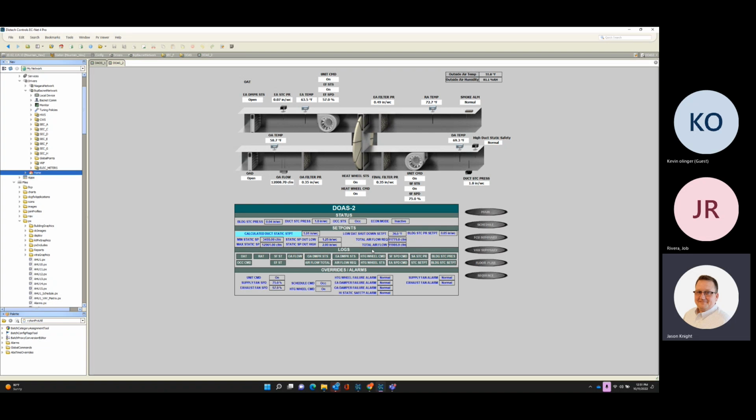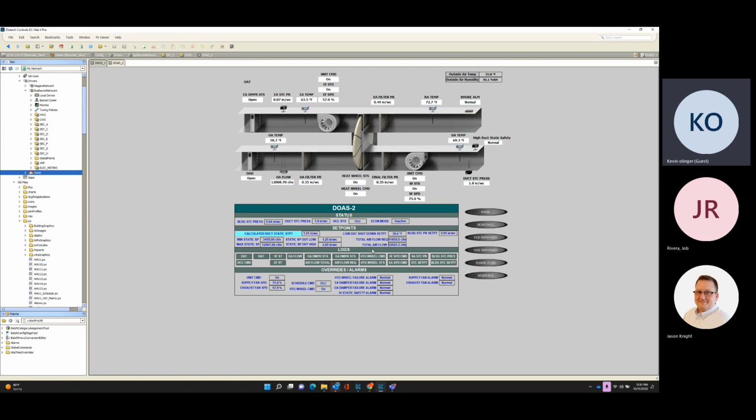Yeah, because typically what they've done in the past, like in a lot of your other buildings, is guessing. The specs all come written. They say, look at the dampers every 5 minutes. What is the average damper position? And then increase the duct static set point based on what the damper positions are, just to make sure no dampers are sitting at 100% for too long.